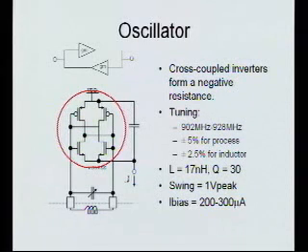So if your capacitor varies by 10%, your frequency is only varying by 5%. You get a little bit of help. So anyway, that's where these numbers roughly came from. We estimated about 10% realistic variation in our capacitors and a 5% variation in our inductors. So hence we need a sort of 7.5% plus or minus coverage.